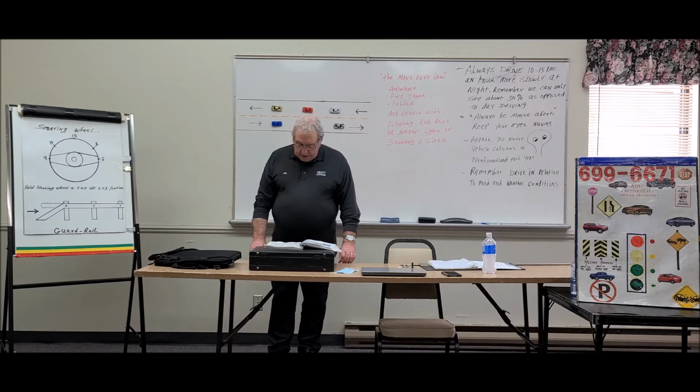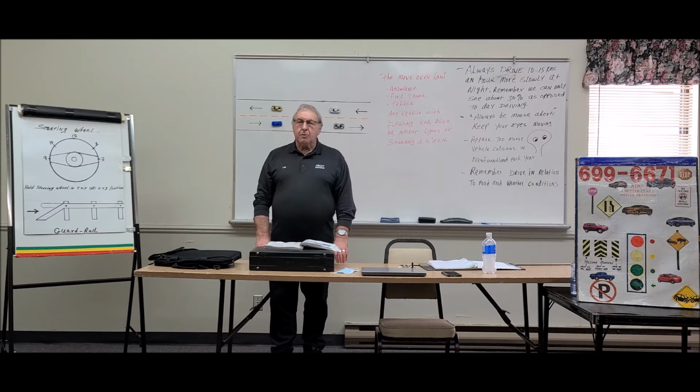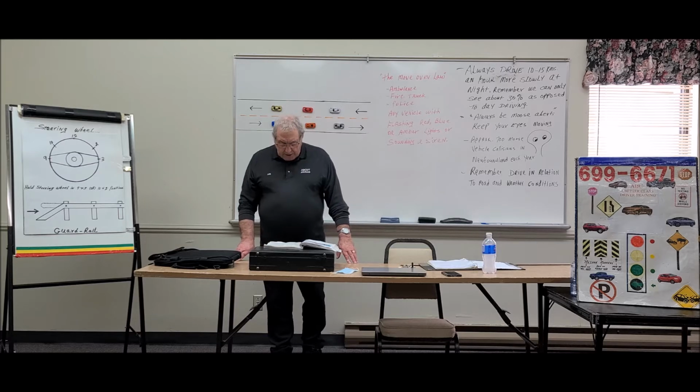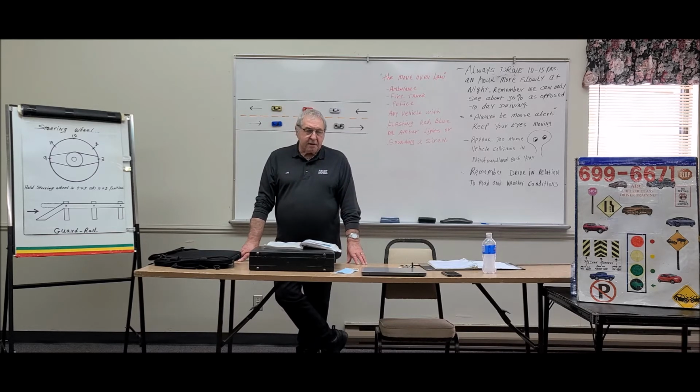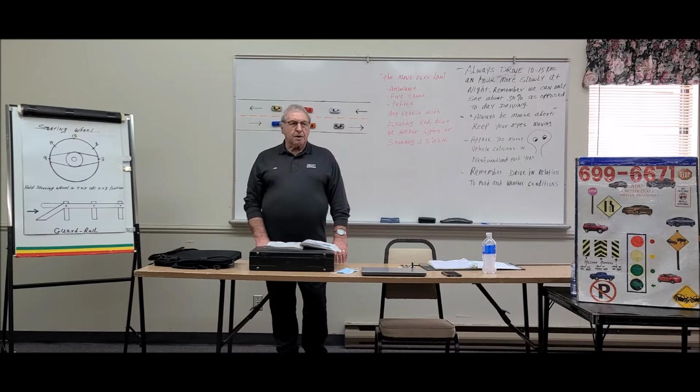The low engine oil level light indicates the engine oil level is too low and should be checked immediately. On newer cars, again, you will get a warning if your engine's oil pressure or the oil is low. You'll see a light flash in your instrument panel. That warns you to say, look, it's time I've got to top my engine's oil up or I'm going to have a problem. But on older cars, that wouldn't be the case, class. You would have to check your oil level in your engine regularly, just to make sure that you've got the correct amount of oil in it. But on newer cars, of course, the computer sort of helps us along a bit in those cases and warns us of things before it actually does any damage, which is a nice feature.